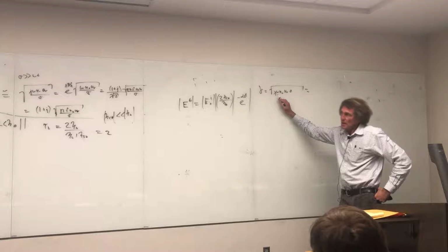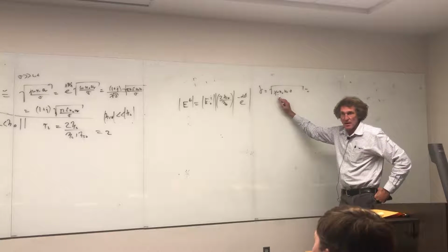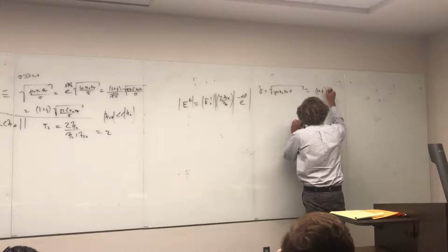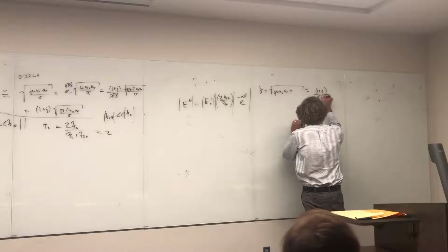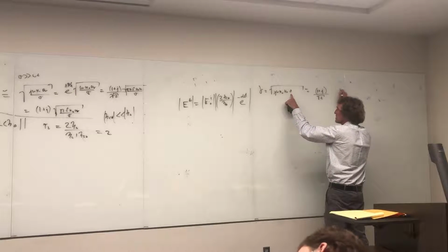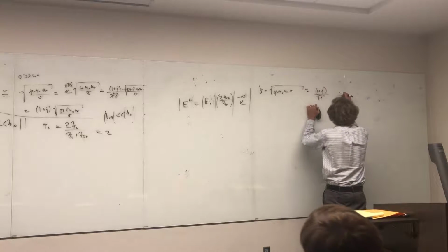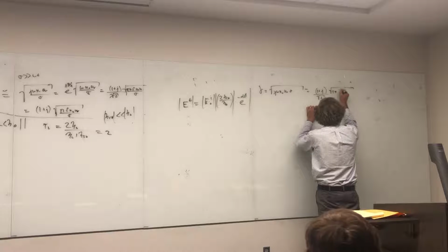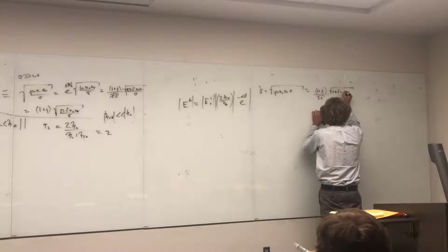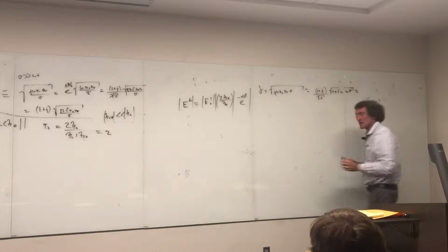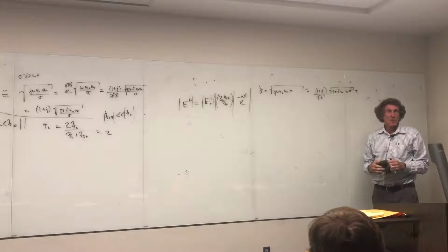Correct, class? And I think, is that still up there? Right? So put it in. You put 1 plus j over the square root of 2, and then times this inside, which is omega mu naught mu relative sigma. Well, omega is 2 pi f. I'm doing this for a reason. This is the way it usually appears. So it's 2 pi f times mu naught times mu relative times sigma. Now, everybody see this? What do you notice here?